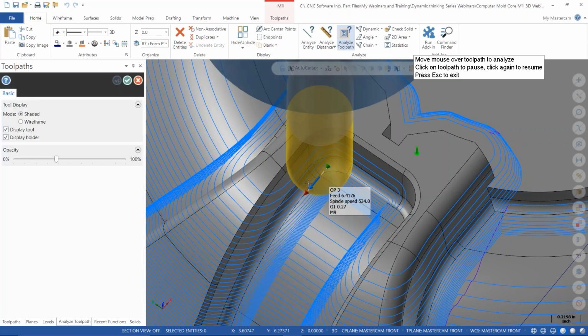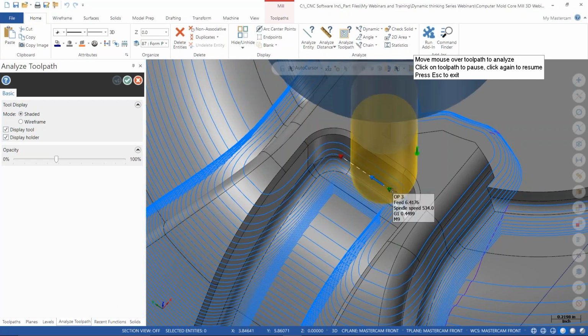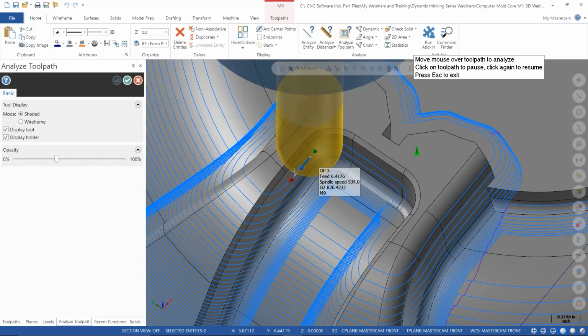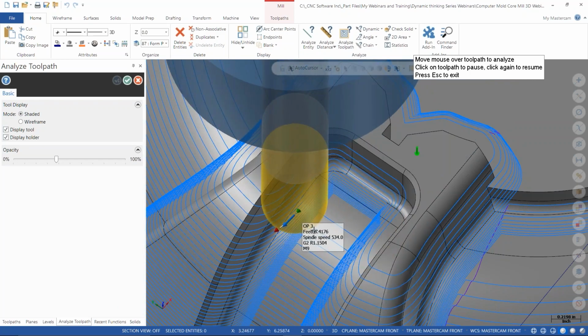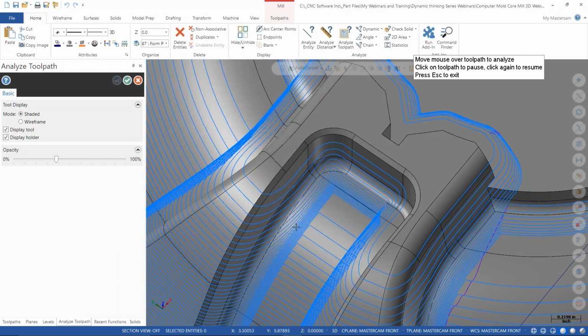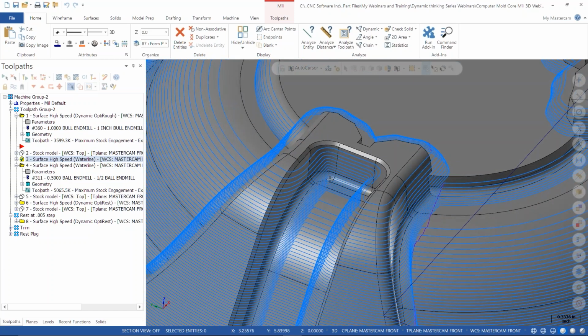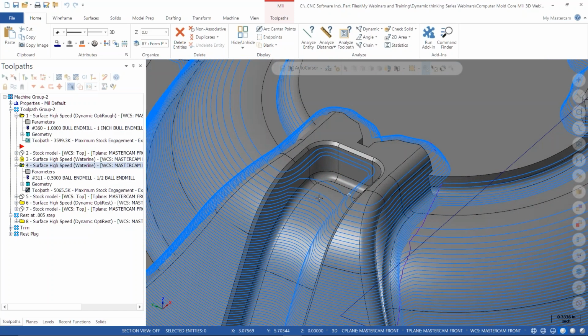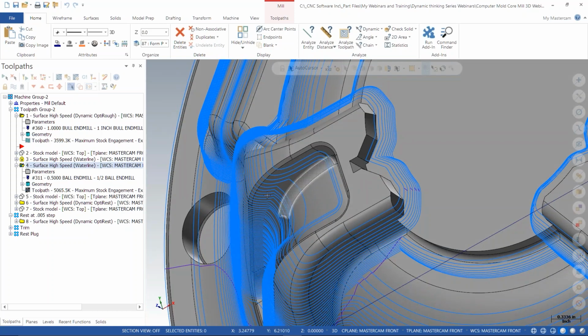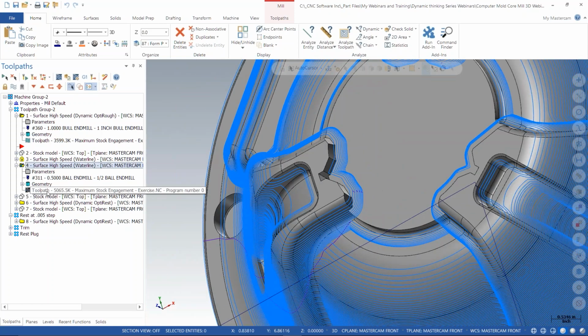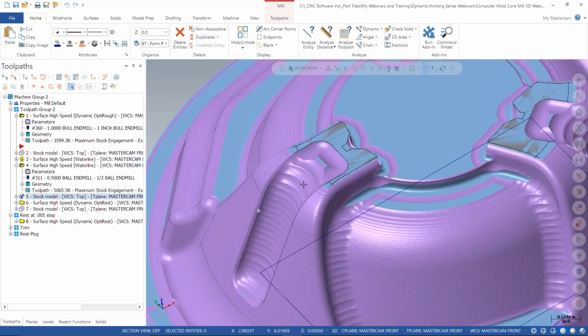And I don't know if this tool would leave an island at some point, and then when it runs across, it's going to hit. It's just not friendly. The step down is what's going to save me, but I could leave material. I don't want to deal with all that. I'd rather it just say, hey, when you get to that stock, just follow it along, only go into it so far, and I'll deal with this later. And I was left with this shape.